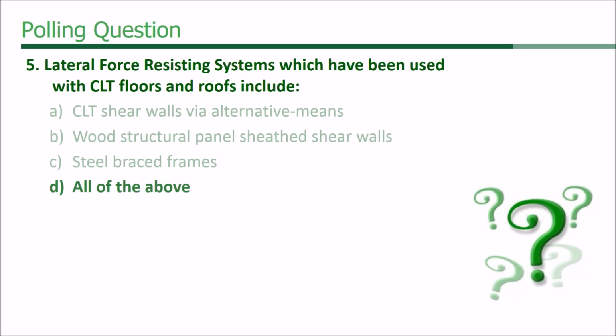They're putting some work into designing that lateral system. The Brock Commons up in British Columbia, that's 18 stories tall. They put a lot of work into the fire resistive design, but they decided to go with a concrete core and not dress that. Vancouver's another seismic region, so they said, well, for our seismic force resisting system, we're going to go with a code accepted concrete core and not take off that byte for this new tall wood project.